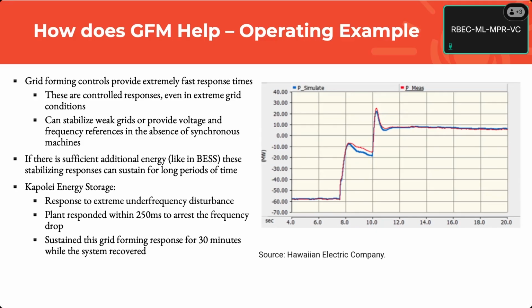Another way of saying it is it's an uncontrolled response, in that if you think of a synchronous machine that's spinning all day long, since there's a big piece of spinning mass there, when you change the terminal conditions, the electrical conditions on the terminal of the machine, the internal quantities, the voltage phasor and angle, don't change immediately. The system changes very quickly, but the internal quantities can't change immediately because they're part of this physics, right?